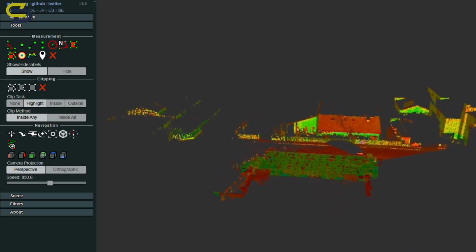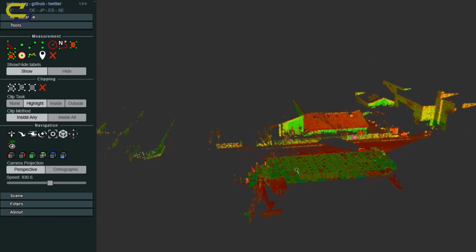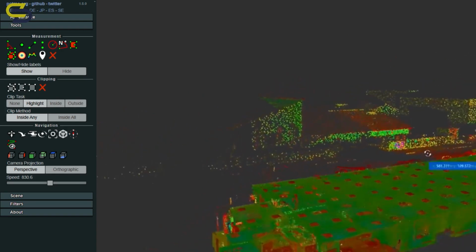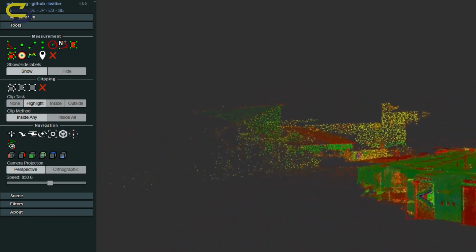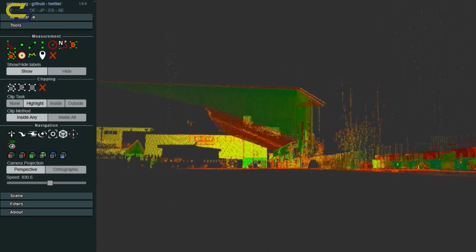In a word, no, you don't need expensive software. Most surveying companies can supply the point cloud via a hosted online viewing platform. These platforms enable you to virtually walk through the surveyed space, take measurements and mark up and annotate points of interest.